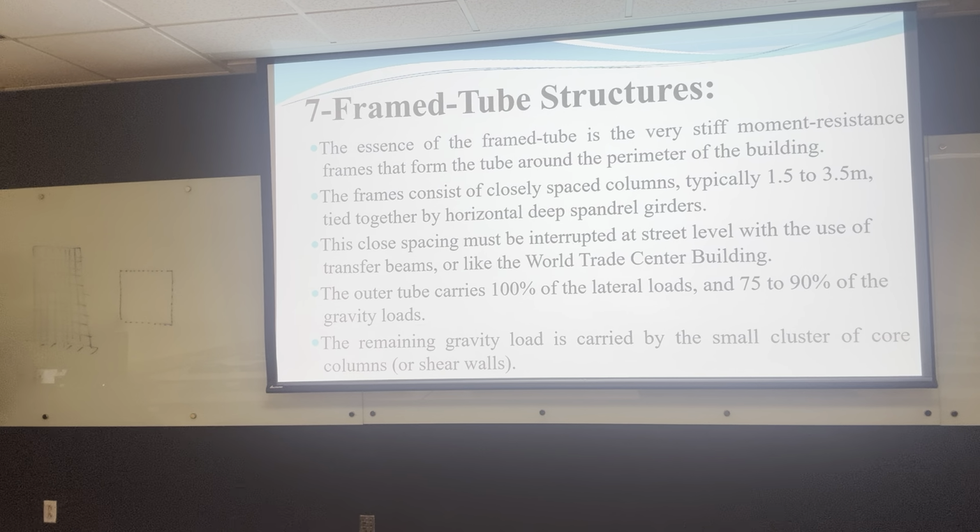So if this building got an earthquake, like let's say it got hit with a force like this, the building wants to bend that way. So all the columns here are going to have stress something like this. All this is going to have tension, and then they're going to have compression, right? So all these columns are going to act like this, and this is going to have tension, tension, tension, and here it's almost zero, and here is going to have compression, compression, compression, compression.